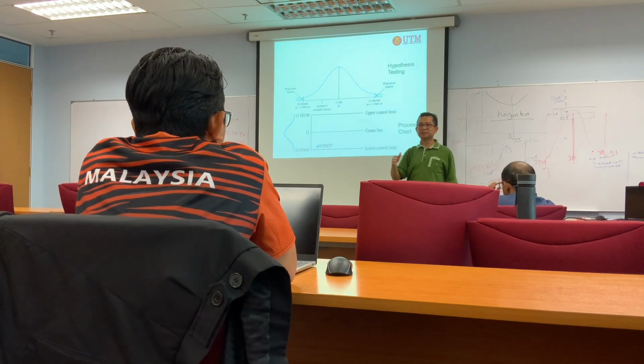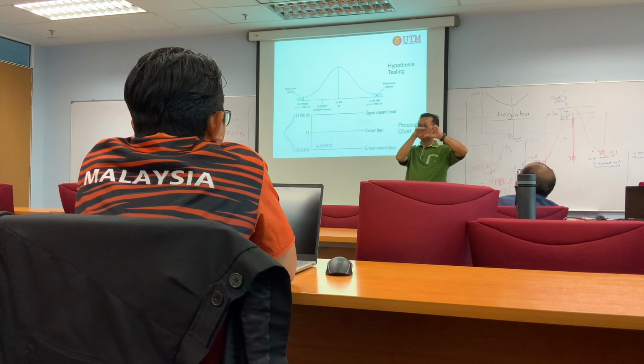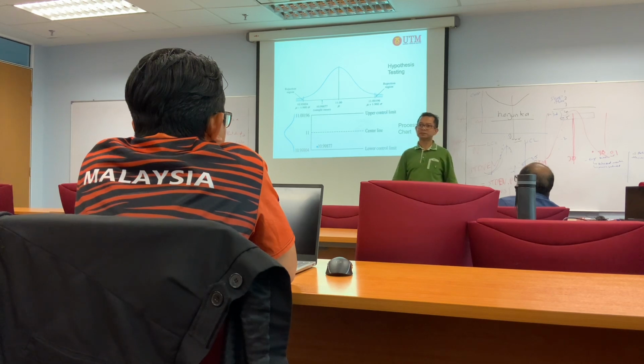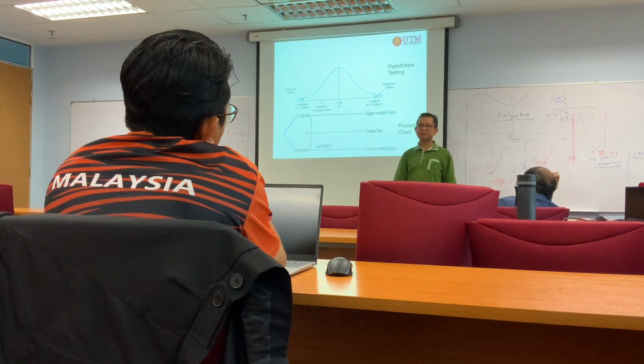For example, machining. Target value is 28 millimeter. We have tolerance, but all the time when we cut, we cannot get 28. We got 27, for example, or we got 28.1. We got consistent around that. But our customer wants 28. So we have to check whether we have a tooling problem or our tooling is okay. We check our material problem because some material is brittle, so that it cannot give us the accurate cutting dimension.